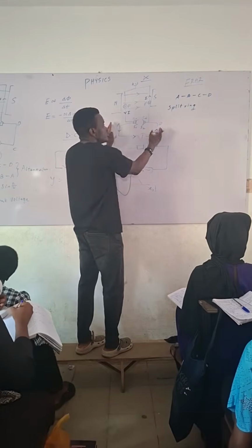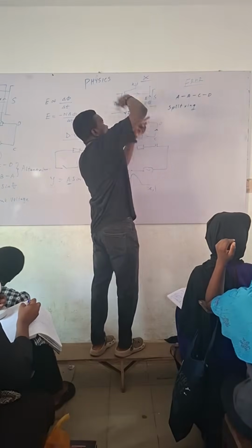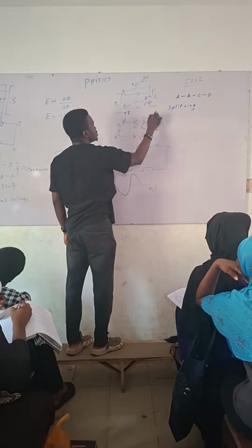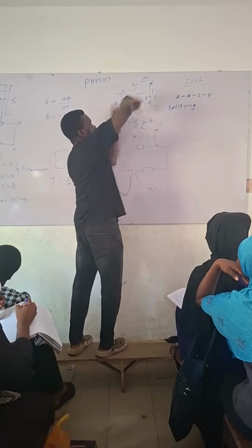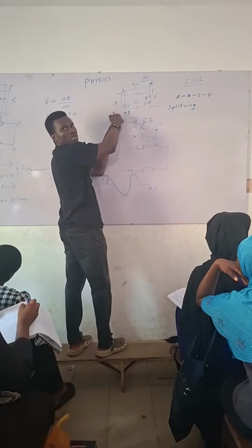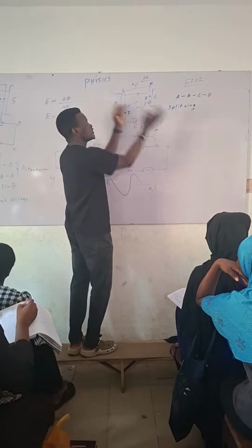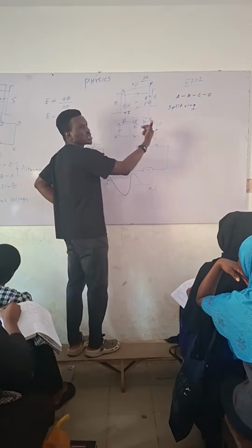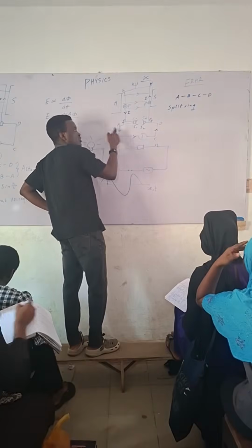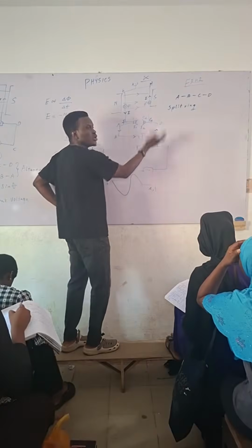So it's designed in a way that this one will not rotate with it. So only the coil will rotate. Now, let's say the coil is E, F, G, H. When you rotate it the first time, E, F will be here, and G and H will be here, right? But this one will not rotate. So even after that rotation, the current will still go up and come down, but that current coming down will still pass through A, B, C, D, because A, B, C, D did not flip.